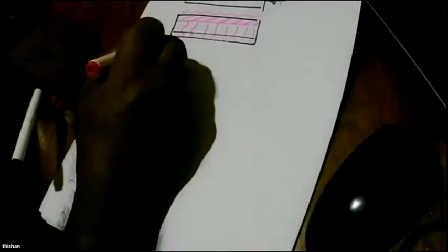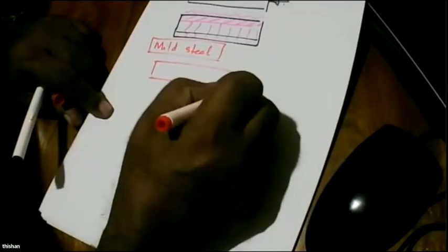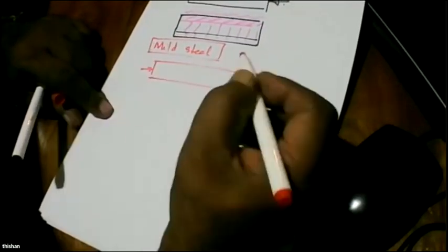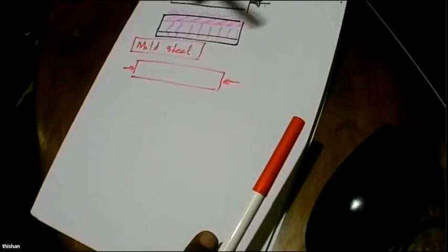And so they did not have a very high strength concrete. And also they used normal mild steel. So when you use mild steel and apply the stress, sometime later they found out that due to the relaxation of steel, the pre-stress vanishes. So initially you can apply pre-stress. After some time you don't get pre-stress, because due to relaxation of steel, the pre-stress vanishes.